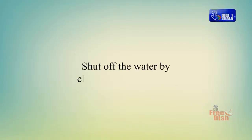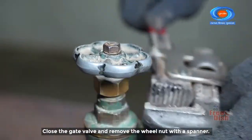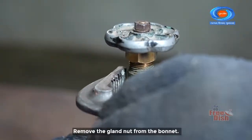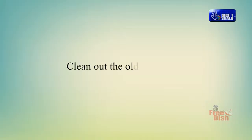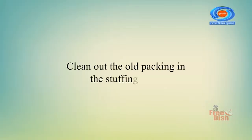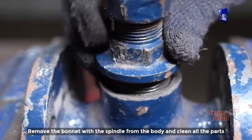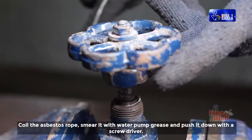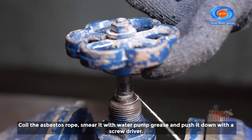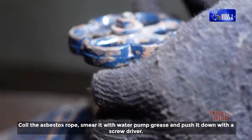Now we are going to see the dismantling and assembling. Shut off the water by closing the main valve. Close the gate valve and remove the wheel nut with a spanner. Remove the gland nut from the bonnet. Clean out the old packing in the stuffing box. Remove the bonnet with the spindle from the body and clean all the parts. Coil the asbestos rope, smear it with water pump grease and push it down with a screwdriver.